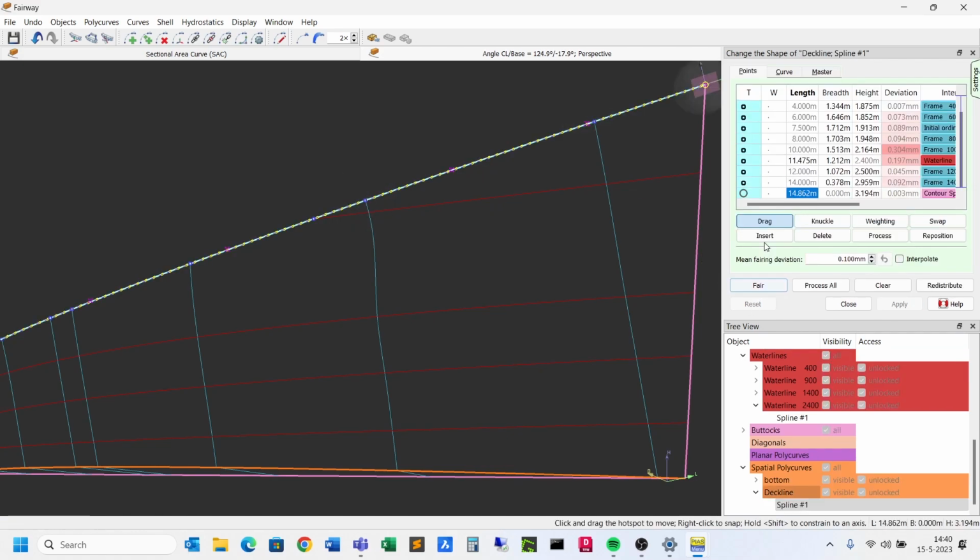If I insert a point there, it depends on the line where you are. But here this is a 3D curve, so it can move everywhere, but I cannot think 3D that well that I'm capable of maneuvering my cursor and have any kind of control. So there's necessarily one direction not free, but if I press the control button, it will switch. So now I have control in the transverse plane, horizontal plane, or the longitudinal plane. And if I press the shift button, it will go up and down. That's actually one of the tricks that I had.